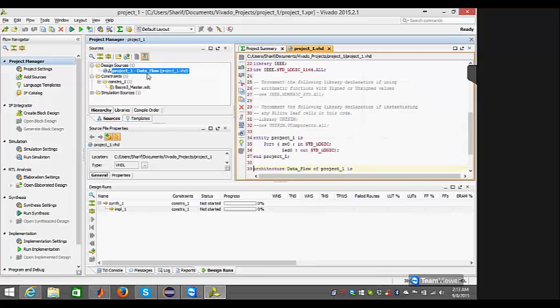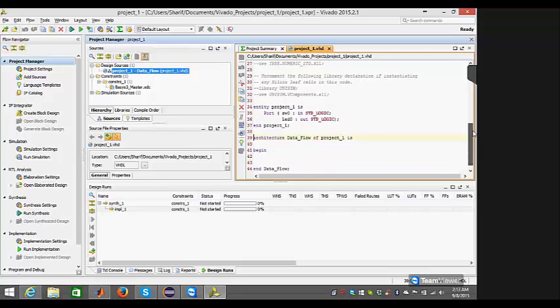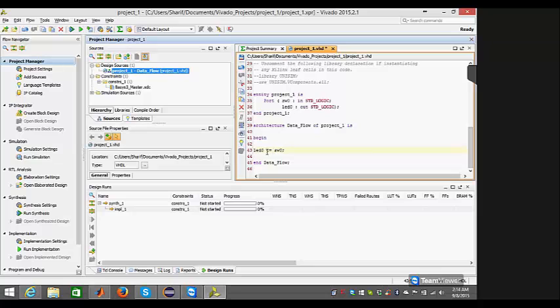Alright, so go ahead and open up the VHDL file. As you can see here, I already have my switch and LED declared in my entity. Once I've done that, I can begin my code. In this case, I'm doing just one LED. And that's it. Since I'm doing it in data flow, I just have switch 0 going to LED 0. And I'm going to save that.